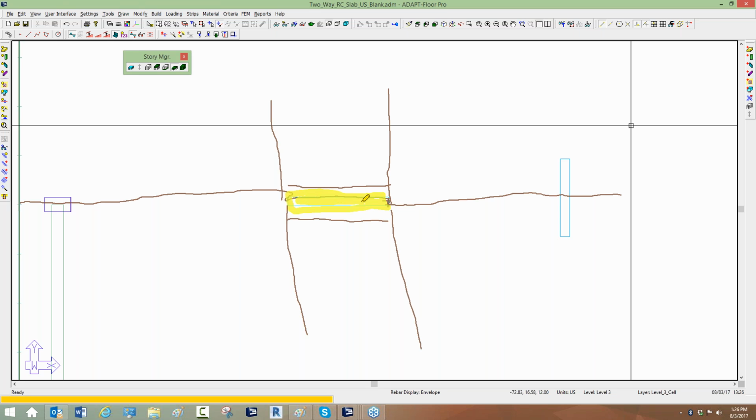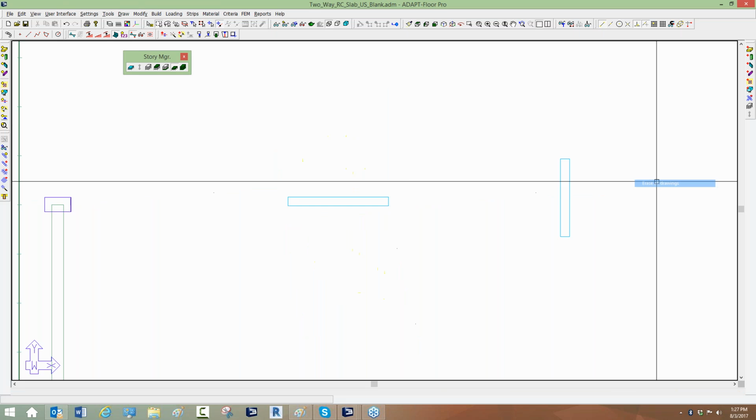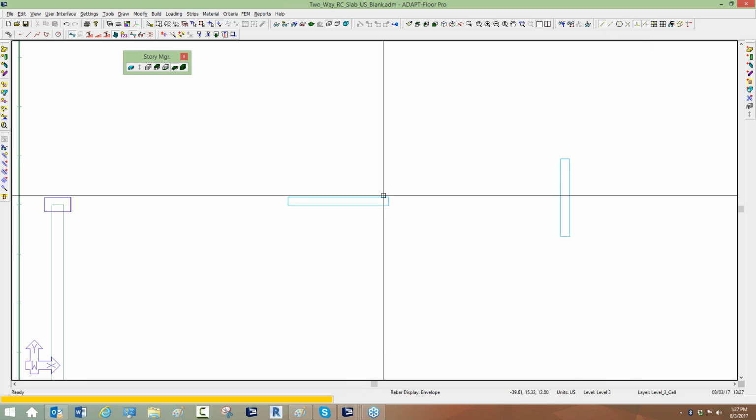The program doesn't design for sections in that tributary, but it does design for sections related to this strip and this strip, which might have design cuts that look like this and look like this. And I'll show you an example of this when we set up our strips, but this would allow you to get reinforcement near the wall but not directly over the wall. So there are certain ways to set up design strips in a more complex way or manner to obtain those types of results.